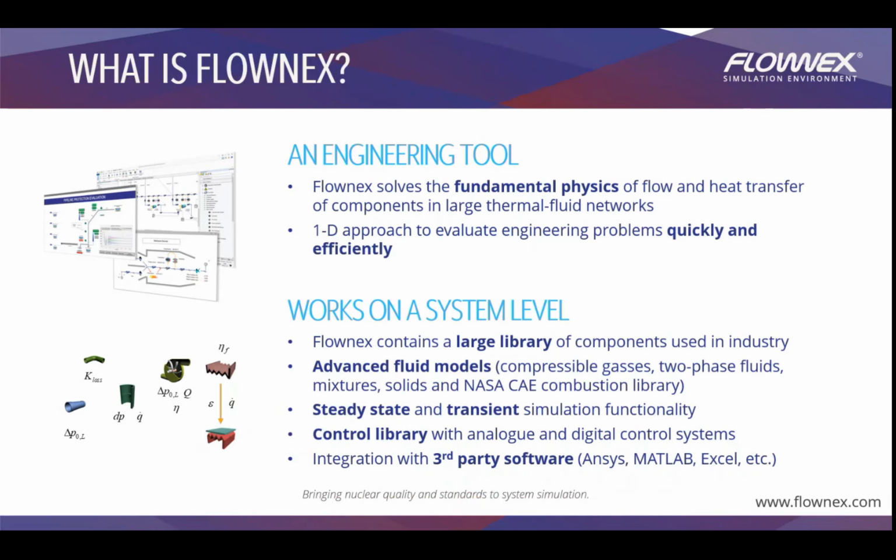So Flownex works on a system level, meaning that it contains a large library of components that are widely used in the industry. We also have some advanced fluid models, consisting of two-phase flow, compressible fluids, mixtures of mixtures, solids, and we also have a library for the NASA CEA combustion library. Flownex can also solve steady state and transient simulations, both very efficiently and quickly.